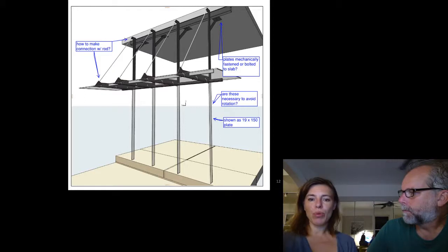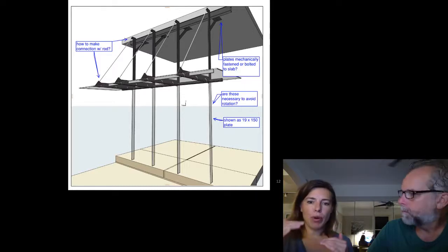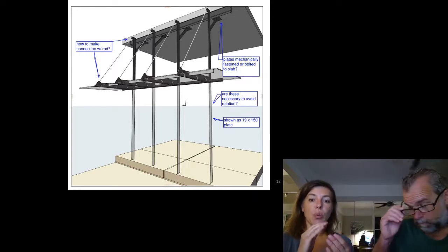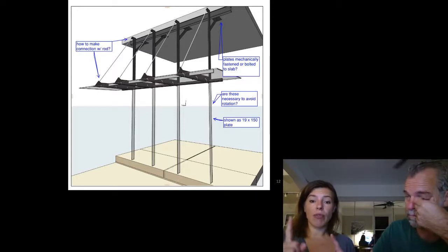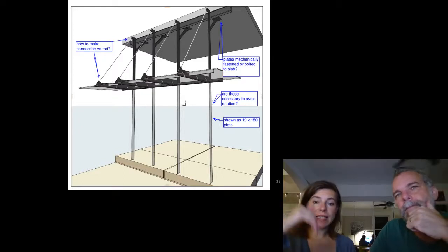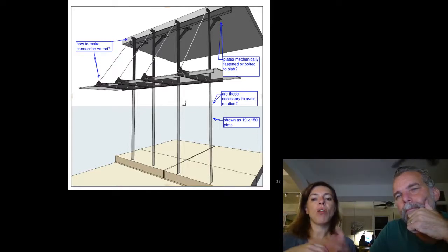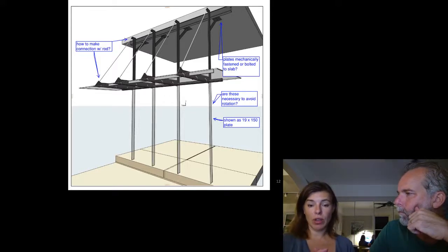and this is the problem, sometimes we go through the process. I had already designed it with the rod in tension, and it was an iterative process because we have to figure out how much we tension it, but it's only being applied for the serviceability condition, so we need it not to be there for the upward strength condition, but to be there for the downward strength condition with the applied tension force. So there's like 3 separate models, or you need non-linear modeling software to look after that.